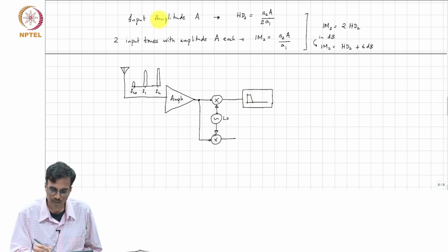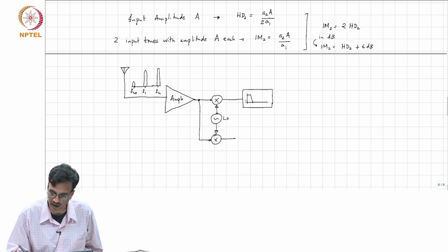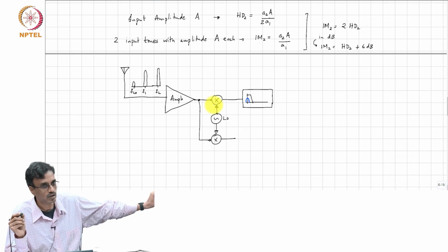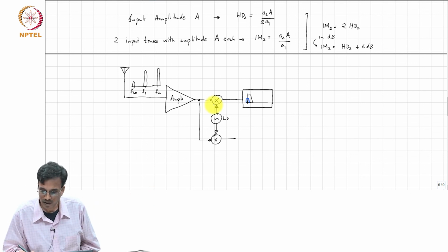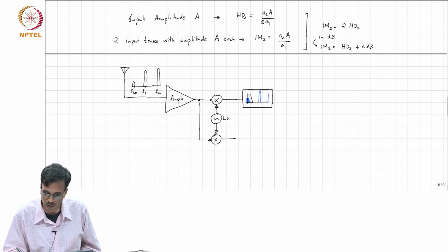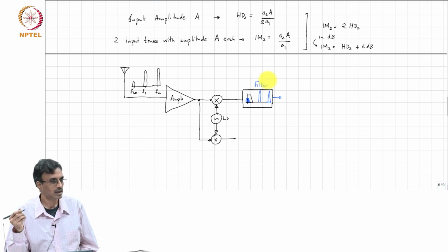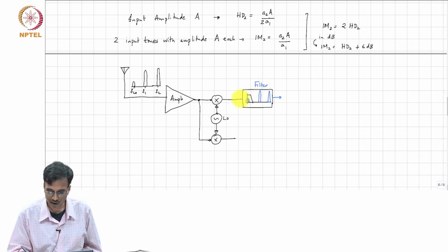The desired channel is basically a small signal which is sitting here, because you have multiplied the FLO with FLO, so you have baseband to baseband. But then you have these two large signals here, and these two can intermodulate through second order nonlinearity of the filter. Remember the filter is made with active elements, and active elements are fundamentally nonlinear.